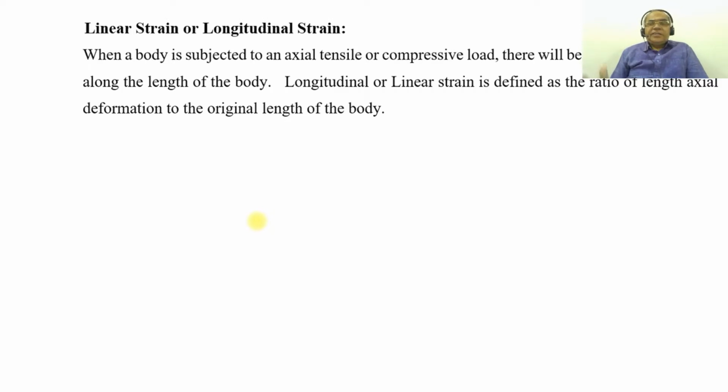Now, in this video, we are going to discuss the linear strain and the longitudinal strain. So, what is a linear strain? When a body is subjected to an axial, tensile or compressive load, there will be an axial deformation along the length of the body. Longitudinal or linear strain is defined as the ratio of the axial deformation to the original length of the body.